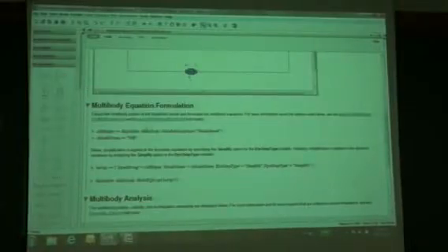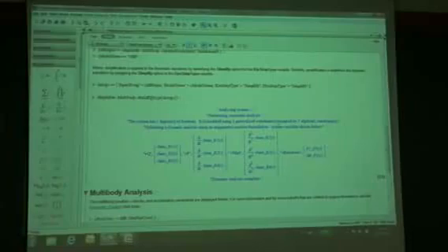These are in a Maple library called MapleMultibody. I'm just going to extract the equations. And now I'm going to build system equations in a more appropriate format. And this tells me that this is a 1-degree-of-freedom system, has 3 generalized coordinates and 2 algebraic constraints.